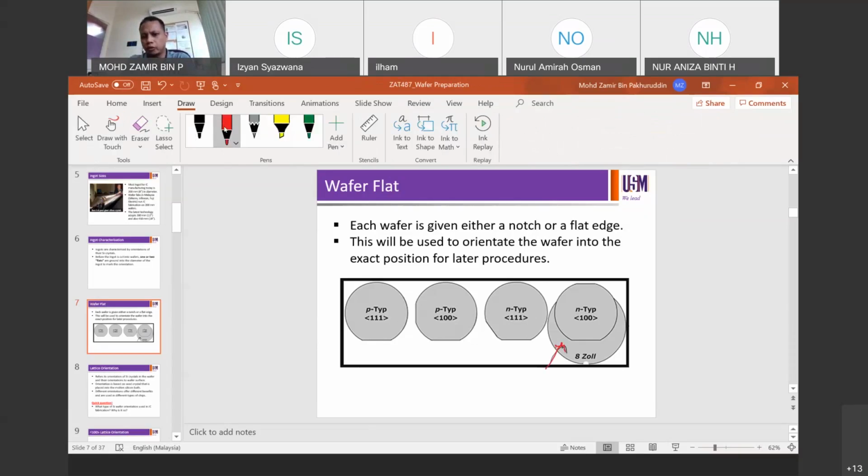We use this one. We have a notch here. This small hole we call the notch. So you normally have a perfectly round wafer. It's not flat, for my drawing here. And you have it like that, with a notch. We normally use the notch in wafer fab. We hardly have flats for wafer fab. Okay, why do we need a notch?